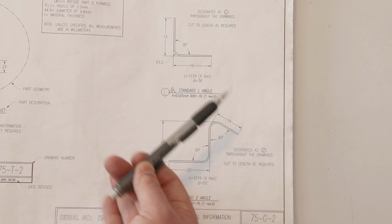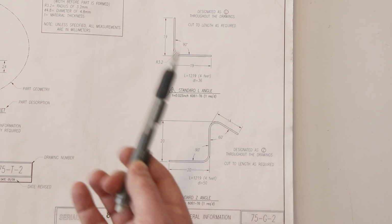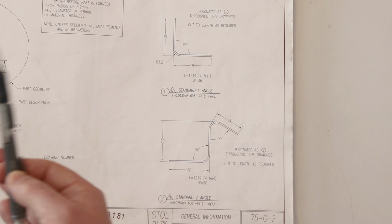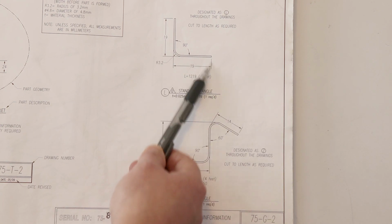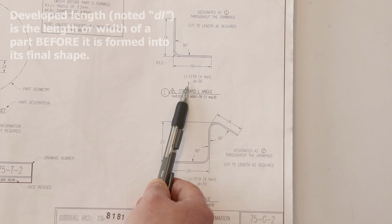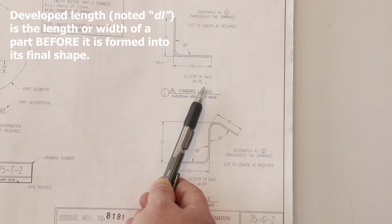We can see here they've only shown us one view of the drawing. So unlike an orthographic projection where you may see 2 pieces of a drawing, they've given us enough information that we can fabricate this with just one drawing. So the developed length is 36 millimeters and the standard length is 4 feet, which is essentially the full width of a sheet of uncut aluminum that you might buy.